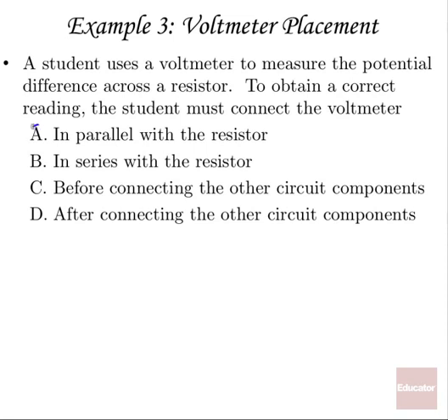Well, right away you should know the voltmeter must be connected in parallel with the element you want to measure, in parallel with the resistor.